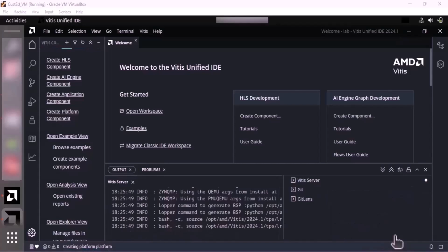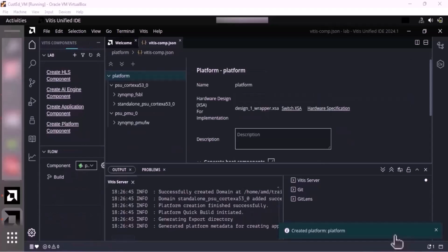The AMD Kria KD240 SOM utilizes both UART ports, UART 0 and UART 1, in its Zynq UltraScale+ MPSoC's MIO. However, UART 1 is the default JTAG or UART serial port, while the hardware BSP in the platform component defaults to UART 0. This means that any print statements in our code will be sent to UART 0. To update the BSP, open